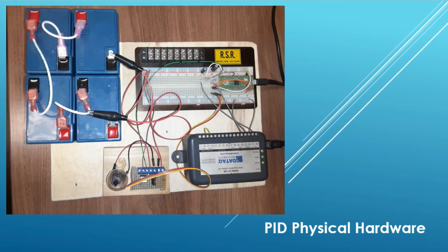This is the hardware setup for the PID controller. As you can see, I have a Raspberry Pi Pico interfaced through the opto device and the FET to control the heater element. On the top of the heater element, I have the temperature sensor, which is a serial link back to the Raspberry Pi. And then finally I have the Raspberry Pi creating pulse width modulated signals that are going in as analog signals to the data acquisition system. And then that goes out through the USB and is plotted on an application on the PC.